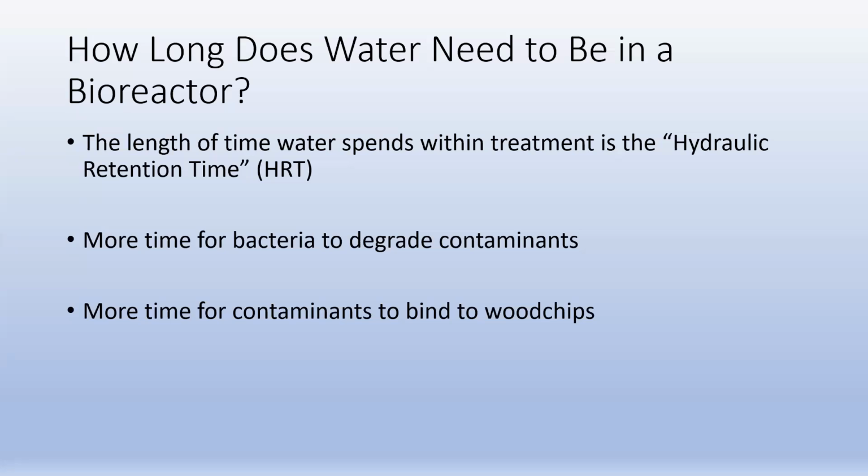Now, the longer you have it treat, that's more time for bacteria to degrade contaminants, right? Those bacteria are going to have access to break it down, and sooner or later, it's going to degrade substantially. It's also more time for contact between the contaminants and the wood chips, and to help foster some of that binding that can occur.